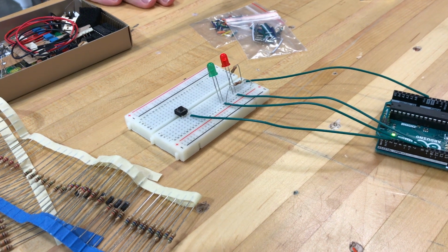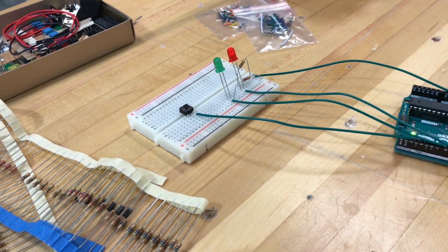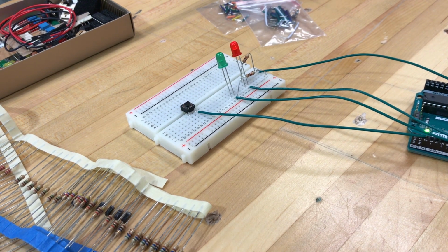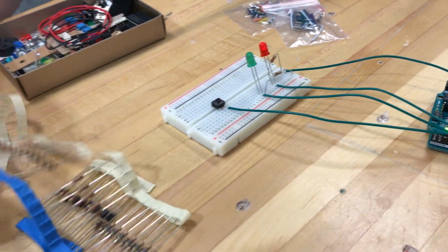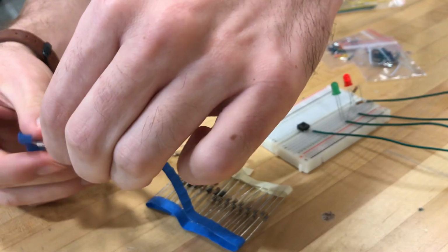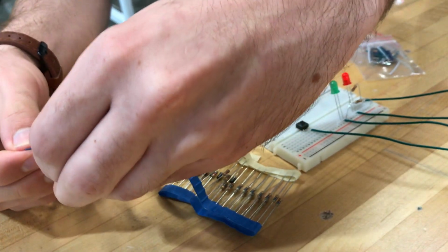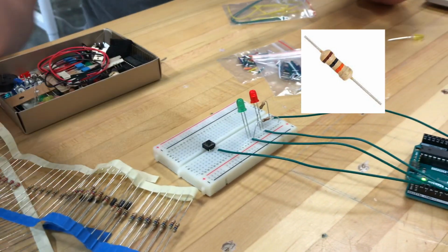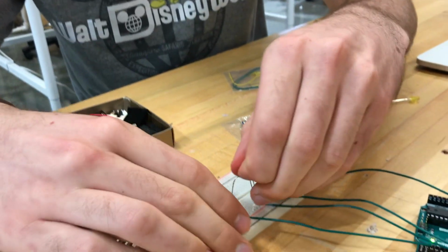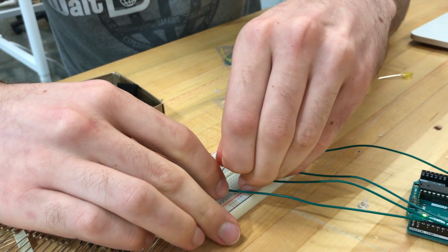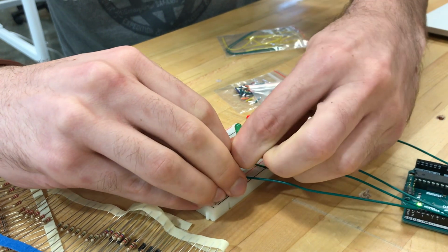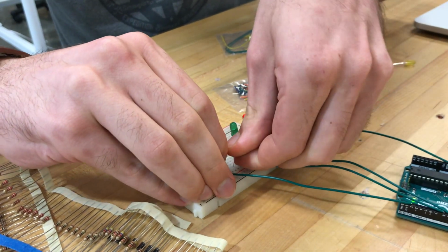The next step is to set up the resistor connected to ground on the same side of the push button as the detection pin. It doesn't matter what resistor you use, so in this case I'm going to use a resistor with the color code brown, black, orange. Connect that between our push button, and then because ground is kind of far away, I'll use an additional wire to get there.